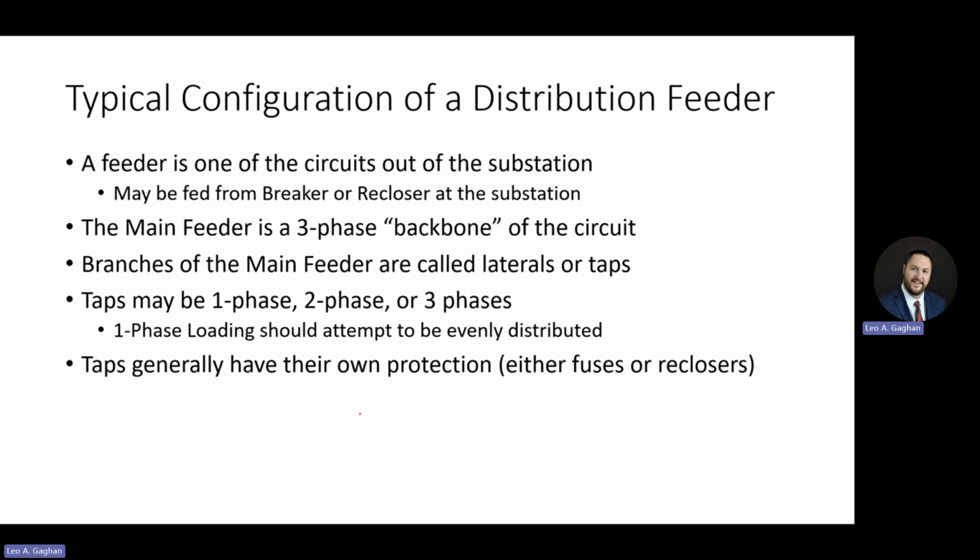If you don't, you end up with an imbalance that can create a ground fault current, and if you have enough of that ground fault current, you can actually trip off. So evenly spacing out that single-phase loading is important. And then taps generally have their own protection, either fuses or reclosers.